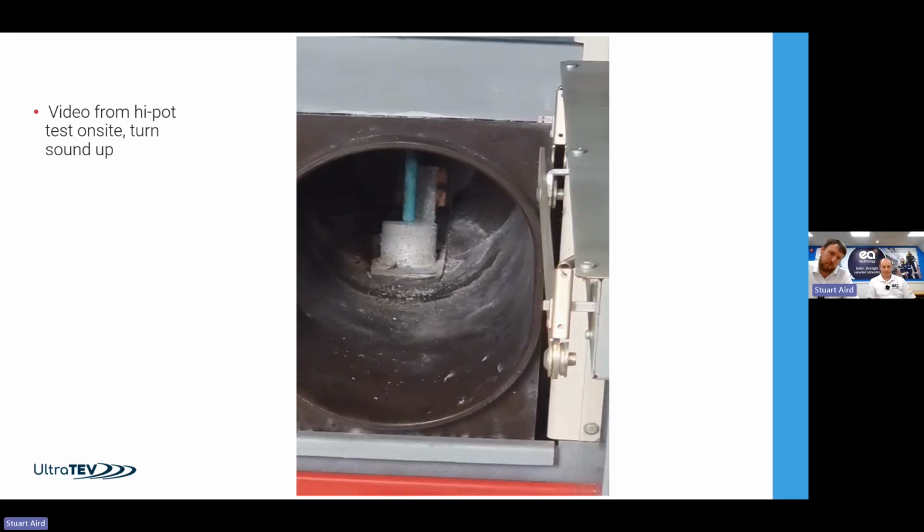Just on the surface of the insulation there, that's starting to arc away, and each one of those sparks is doing a little bit of damage. So it's some energy release, it's eating away at that insulation. And if you could zoom in on that, you'd start to see a treeing effect. And that treeing effect is why you get a much higher number of pulses per cycle, number of events per cycle, and you get an internal discharge. You've got multiple discharge points going on at any one time. And that's heading towards that earth point and eventually to a flashover.